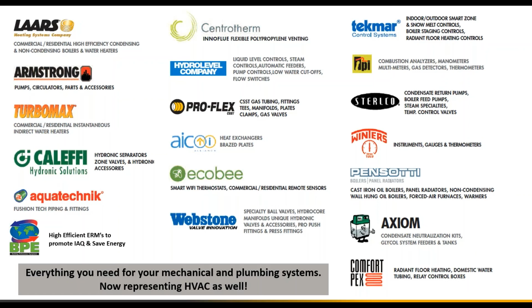So when it comes time to redesign and reconfigure, to get these people pretty much code compliant, if you want to call it that, a major look is going to have to be at the building envelope. If you can tighten that up, then of course you can utilize lower temperatures. It ends up being a big snowball effect. You tighten it up, you need less energy to begin with, and on top of that you can use lower temperatures and get the condensing with the condensing boilers.